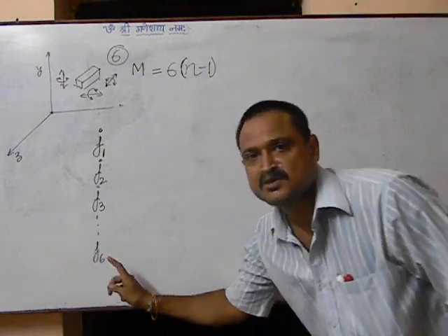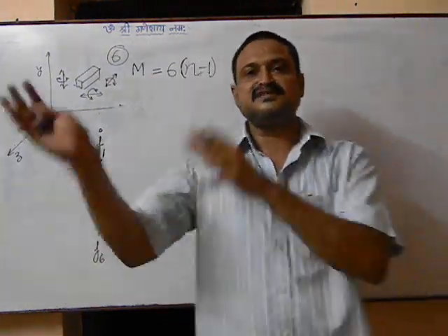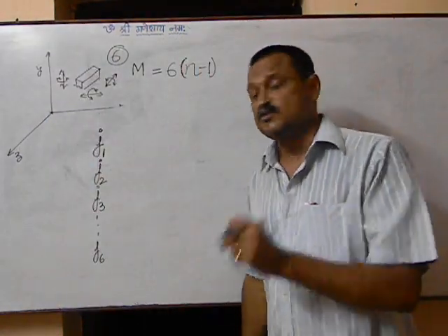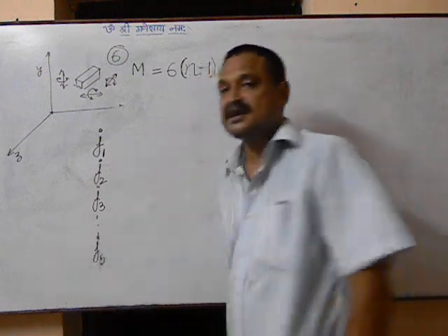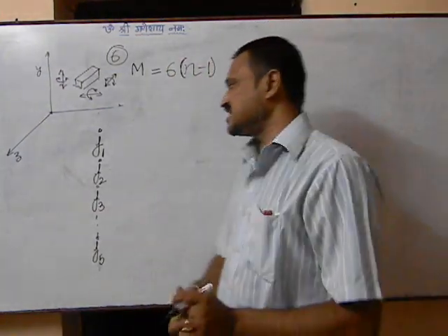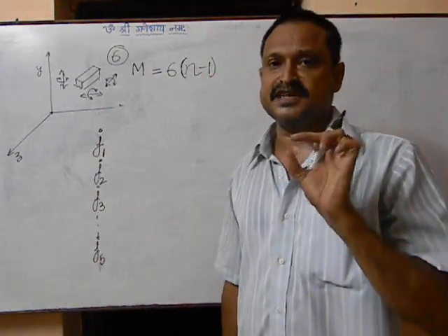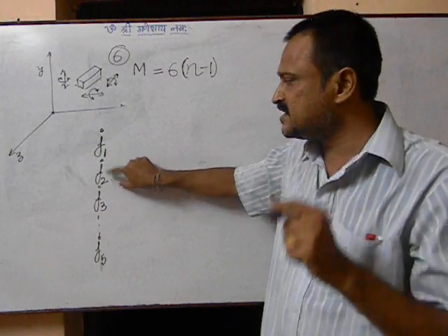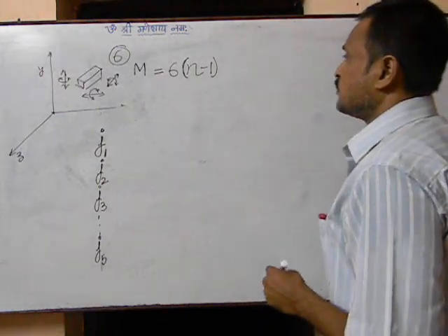Now, will it be possible to have 6 degrees of freedom? The moment I say a joint has 6 degrees of freedom, that means it is free to move in space, which is not possible for a link involved in a joint. So the maximum possibility is a joint with 5 degrees of freedom in that kinematic chain, right? So J1, J2, J3: J1 is the number of joints with 1 degree of freedom, J2 is the number of joints with 2 degrees of freedom, and so on.